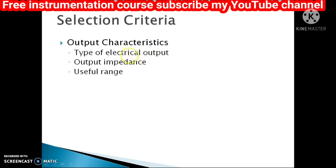The last selection criteria is the output characteristics. Under this we have type of electrical output, output impedance, and the useful range. The type of electrical output, such as voltage, current, time functions of amplitudes, should be such that it matches the next system. Usually we would need to manipulate, either amplify the signal or convert it into digital, for proper use.